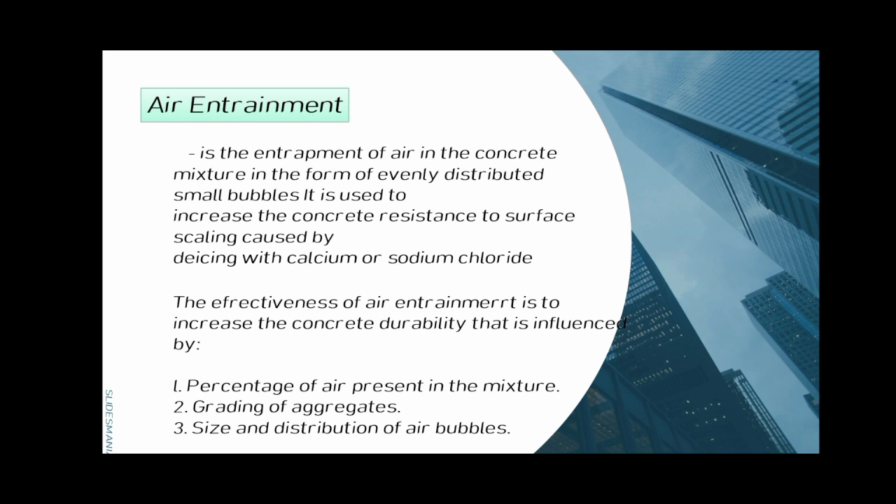Another advantage of air entrainment is improving workability and reducing bleeding in fresh concrete. The effectiveness of air entrainment in increasing concrete durability is influenced by: number 1, the percentage of air present in the mixture; number 2, grading of aggregates; and number 3, the size and distribution of air bubbles.